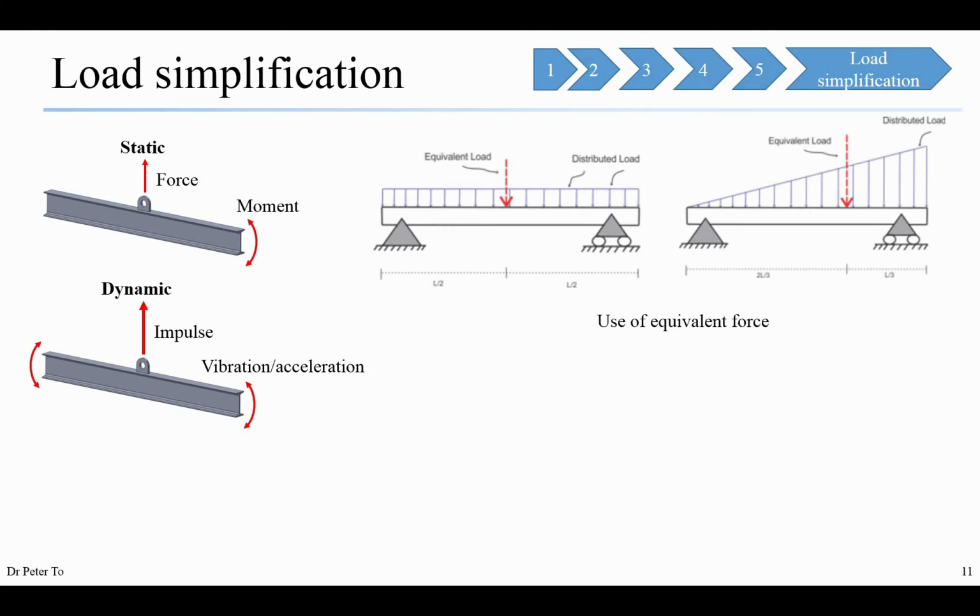The equation of statics comes from Hooke's law, where we have F = Kx. And we have the strain epsilon equal to the derivative of u by x, where u is the displacement, and our stress sigma equal to E times epsilon. In general, we have the vector of strain epsilon equal to the derivative of u by x, where u is a vector of displacements and x is a vector of positions. And the stress vector sigma equals the elasticity matrix times the strain vector.